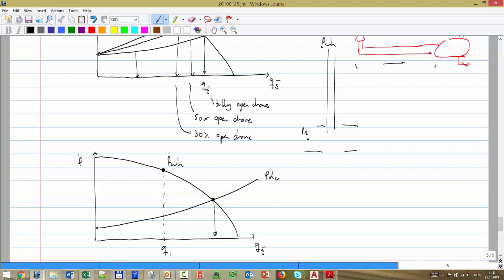I have a high pressure at the wellhead. But I really require, on the pipeline, a low pressure to flush against the separator. So in terms of energy, I have more energy than what I need. So I have to put an element to bring down that energy all the way down here. So I have to put a choke that provides me that delta P.